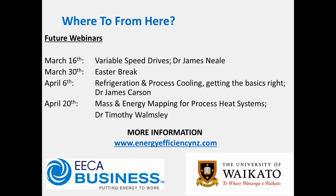Often you find that if you're using a chemical vendor to provide your boiler chemistry services, they will have them as well. If you ask for some dissolved oxygen testing to be carried out, I know Nalco and GE and things like that have the equipment and they can come and do it. All you've got to do is connect up to a 3/4 inch Swagelok port, and you can run the instrument and away you go. I actually have one myself as well for doing R&D work and investigation work at client sites, and they're maybe $6,000–7,000 New Zealand for a portable unit, but less for a permanently installed one, and they work quite nicely.